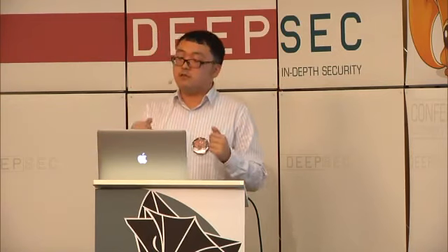So to achieve scalability, HORNET leverages a state offloading technique. In general, in the setup phase, instead of storing the state locally, each router will insert its state into the setup packets, and the source will collect those states from all nodes from the setup packets.